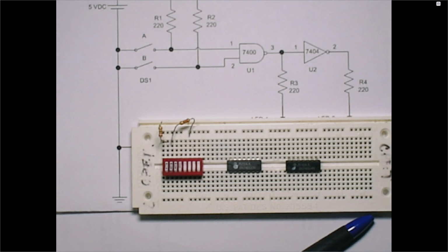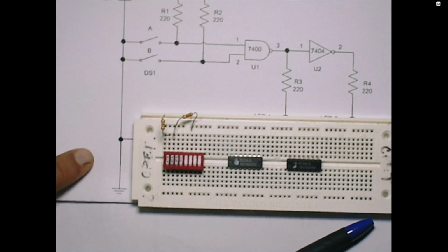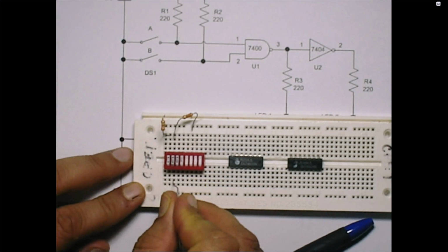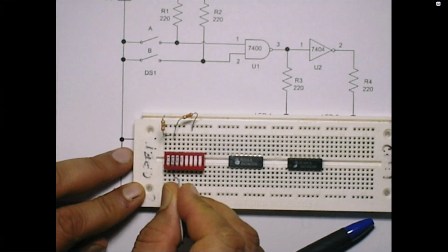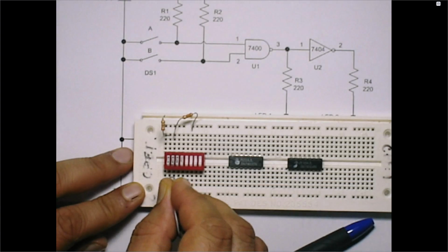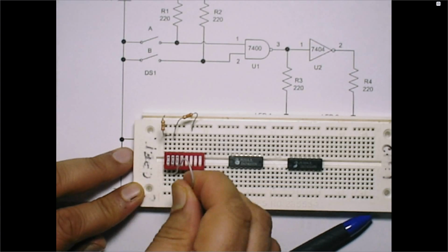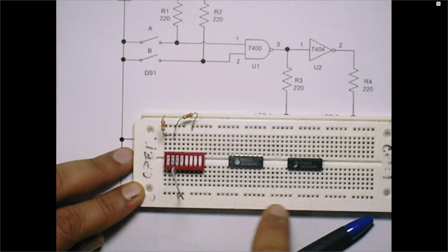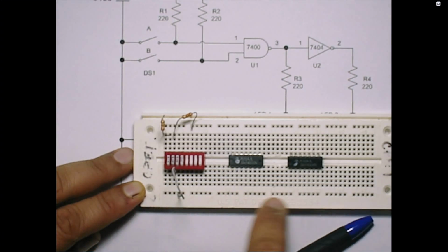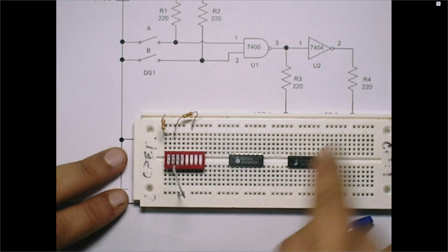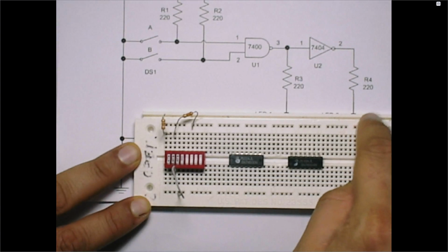Now you also see that with the switch we have a ground connection, right? So for each of the switches we are using, we'll be running a wire from the other side. You see this from this side. For the same two columns, we are running the wire from any point in this column to the ground. Now this bottom row here will be used for the ground. Remember, once you go to the lab, we'll connect the ground to this bottom row. We'll connect the VCC, meaning the power voltage 5, to this top row.